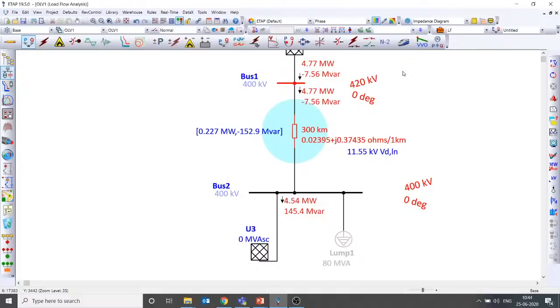Okay. How to tackle the problems that arise after load flow, which are critical, marginal, etc.? It depends upon the acceptable criteria for voltage, equipment loadings, etc. When your voltage is within plus or minus 5%, that's fine. But if it is beyond 5%, then it is not acceptable, so it is critical at 400 kV. But if you look at 415 volt, even up to 10% is acceptable. So it all depends upon the criteria which the electricity board or the local regulation sets. That's to answer the question from Abhijit.